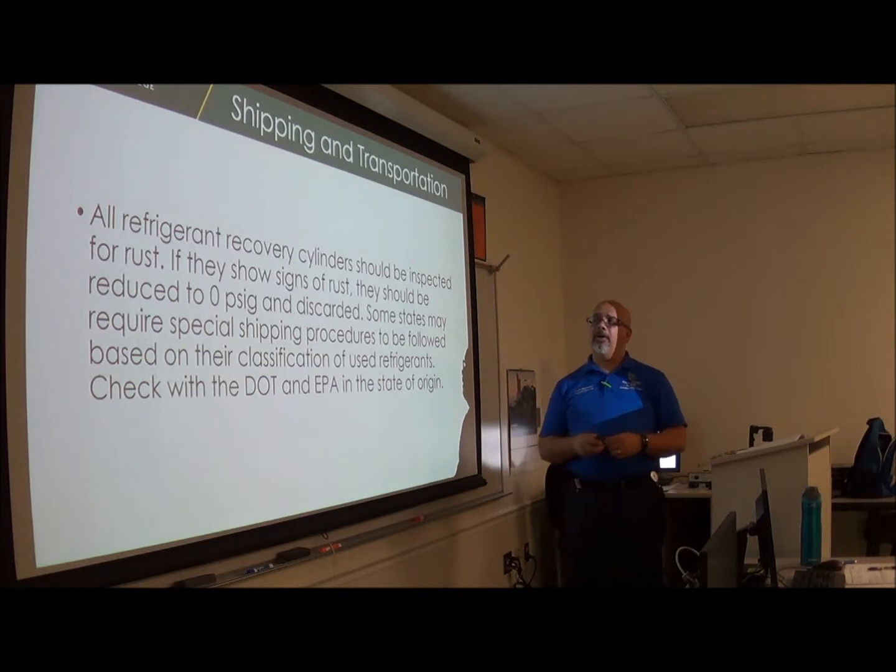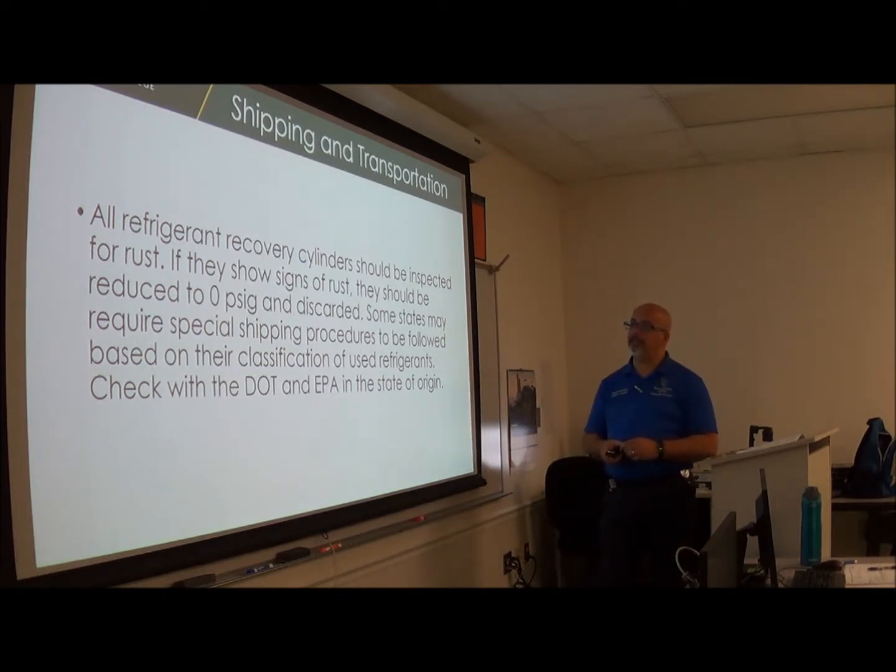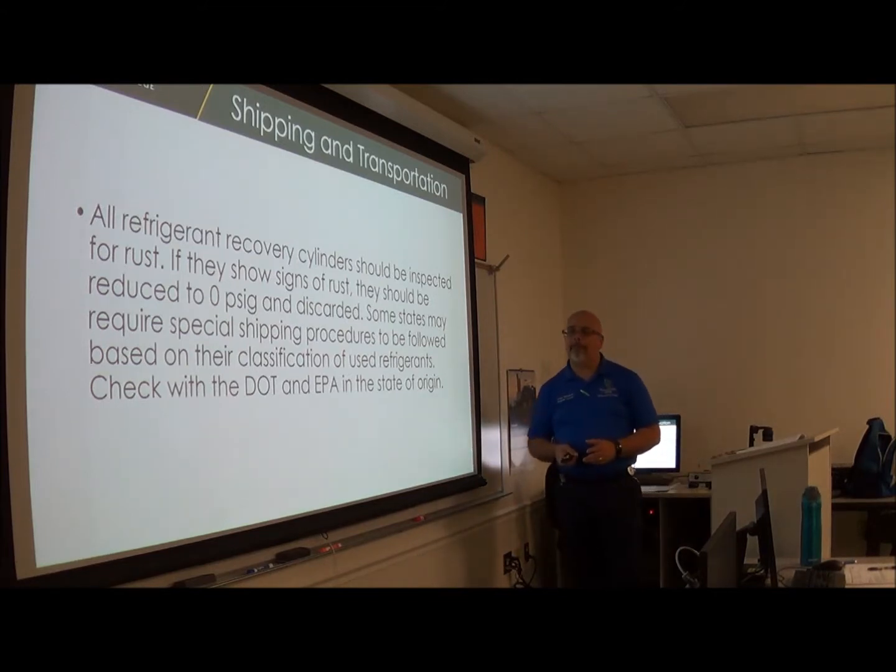All refrigerant recovery cylinders should be inspected for rust. If they show signs of rust, they should be reduced to 0 psig and discarded. Some states may require special shipping procedures to be followed based on their classification of used refrigerants. Check with the DOT and EPA and the state of origin. Okay?